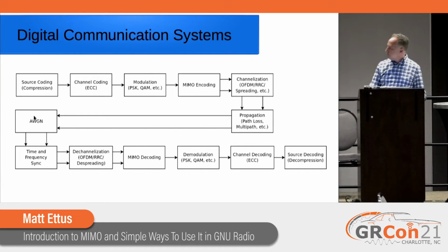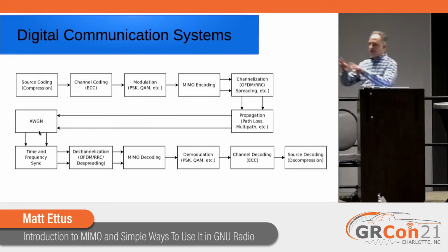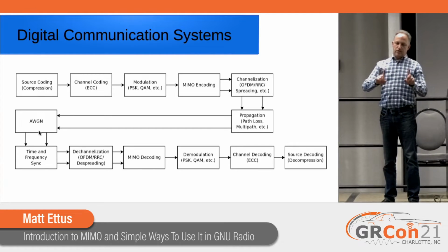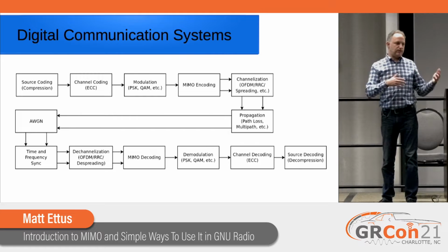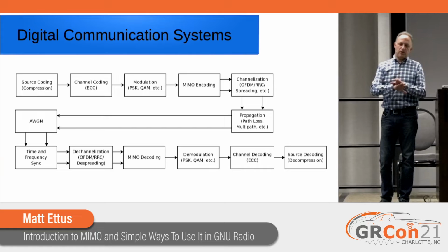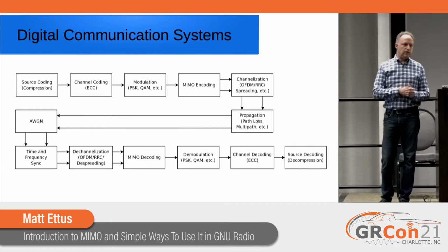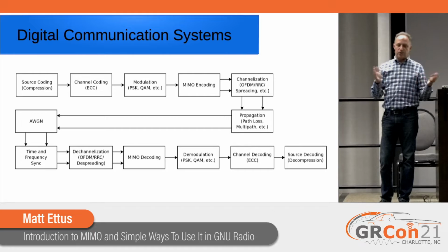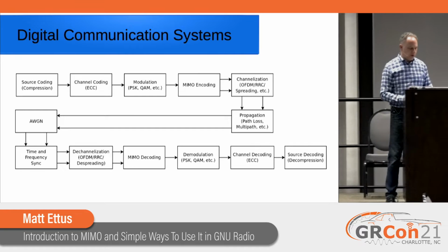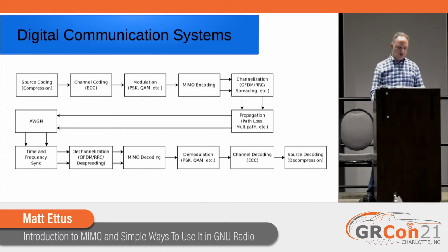And then at the receiver, you get your AWGN, right? And that's why your noise should be decorrelated between the two receivers, because it's really receiver noise. Even if it's thermal noise or atmospheric noise, as long as the antennas are not highly directional, large, like SETI kind of antennas, they will have independent noise. When they don't have independent noise in radio astronomy, it's because you're attempting to do interferometry, and you do want the correlation, and that's how you control the direction. But for our purposes, you can assume the noise is decorrelated here.